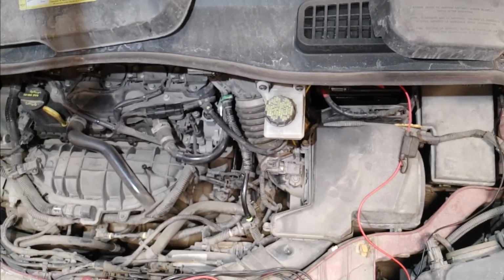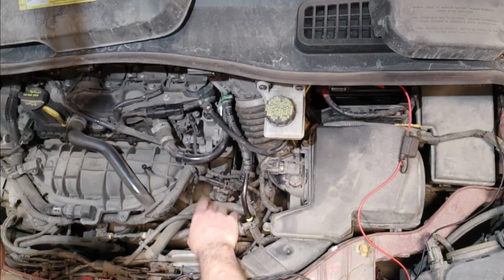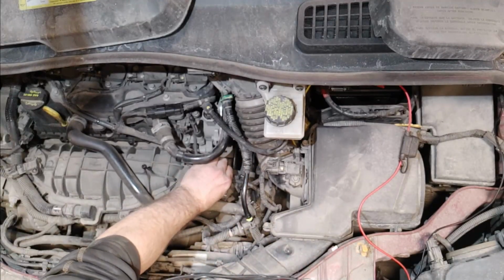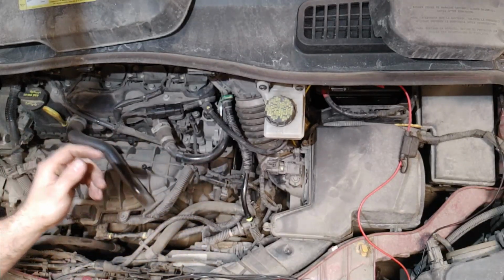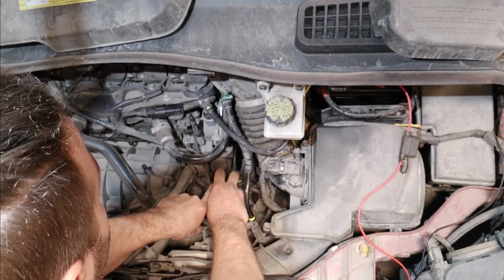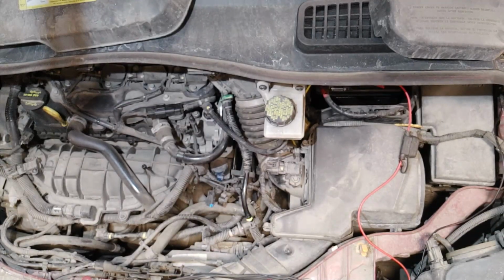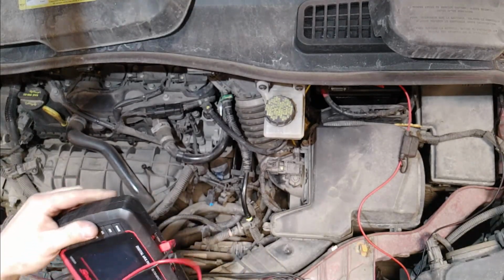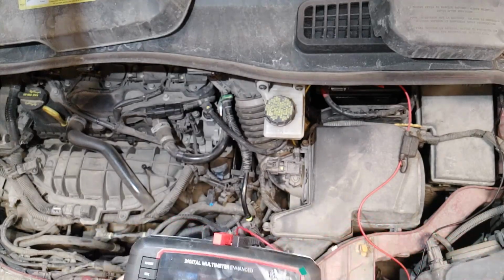So your coolant bypass valve C sits here on the front of the engine. It's this guy right here. So what I'm going to do basically is disconnect him first, if I can get to him. Okay. And all I'm going to do is measure the resistance of the valve. Now, if I have no resistance, my valve is shot, and if I have resistance, I'm going to check my control circuit. And if my control circuit checks out, then I'm going to verify the valve a little bit more in depth. We're going to do some actuation tests, see if it works and whatnot. So first things first, let's get out the multimeter. Set this on ohms. Hopefully everybody can see.